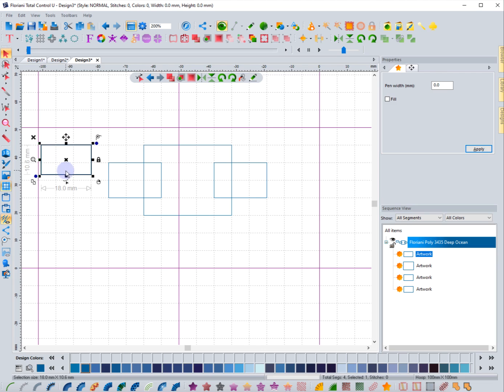Like, for example, if I can get this one to snap to this side, when I want to snap it to this grid line, you'll notice that I'll have a difficult time to do that. See, it wants to snap right here because it's actually trying to snap to that line as opposed to this line. So just a little trick I've noticed is I need to click it and drag it a little bit and get it to snap to that edge.